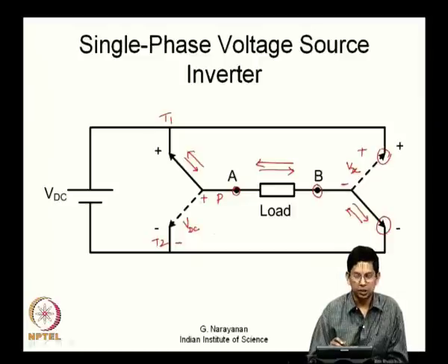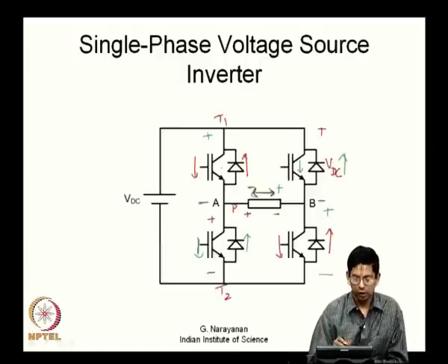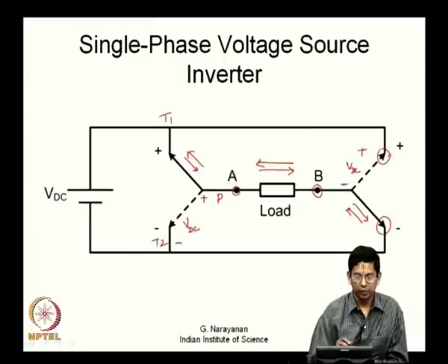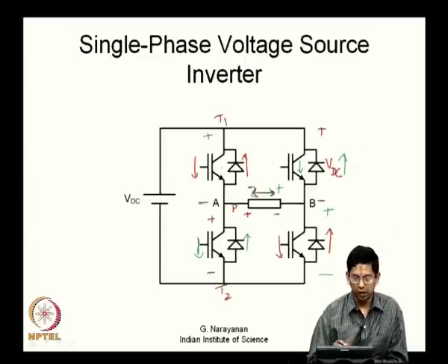What we want here is between a pole P and let us say throw T1, we wanted a switch which has bidirectional conduction capability, and therefore, you have an IGBT and an anti-parallel diode which has that bidirectional current capability. Then you want, let us say, between P and T2, when P and T1 are connected, P and T2 should be able to block a potential with this polarity. You see that you can block it with this polarity.